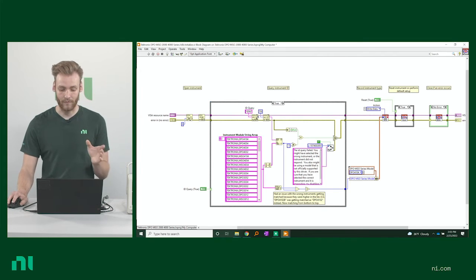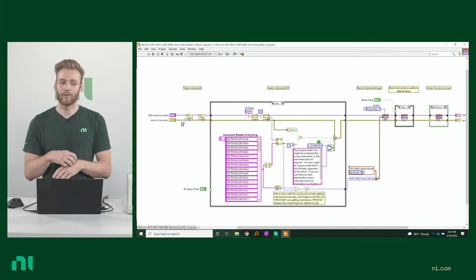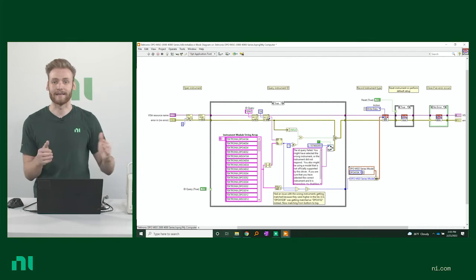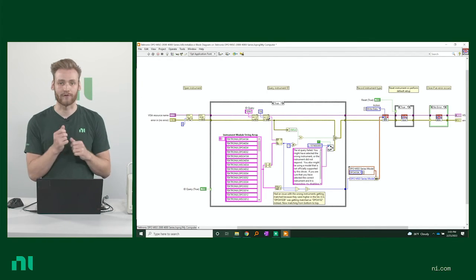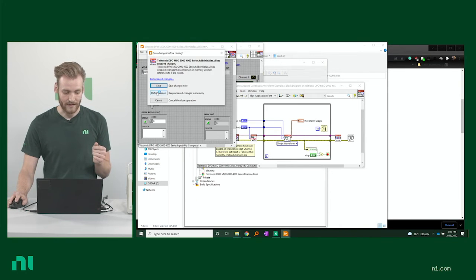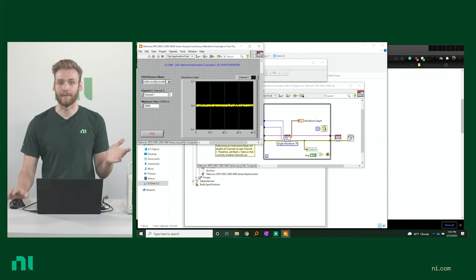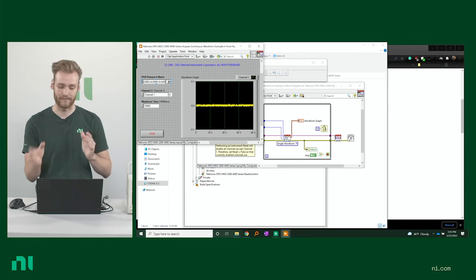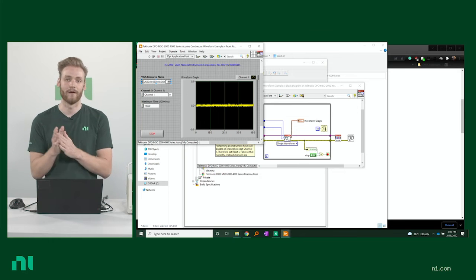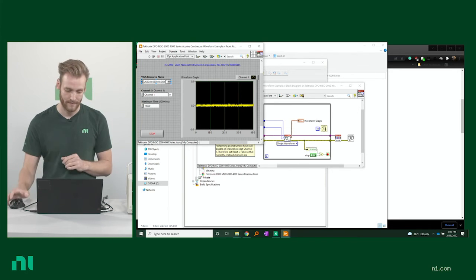And the great thing about the fact that it's using VISA is that you don't have to worry about whether you're communicating over Ethernet or USB. If I set all of this up and built the whole program using USB and then decided, oh, I want Ethernet because I need a longer connection type, you could simply switch and then input the changed VISA resource name, because that'll change if you connect over Ethernet, and then everything will run the exact same way because VISA is just handling that lower level connection. You're just telling it what you want it to do. It's handling how it's actually being sent.